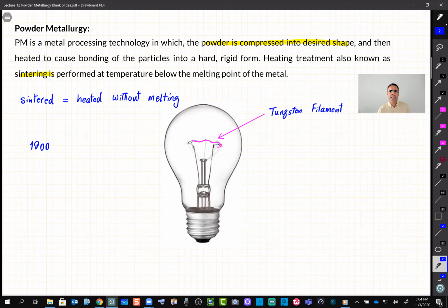Another thing that you may think of is a pen, maybe I have one here with me, a regular pen, which has one of those ball points. That tiny ball point, think of any other approach to make those tiny balls. For example, casting maybe is not a good way to make those, right? And machining, of course not, to make such a small sphere. So powder metallurgy is a common way to make those balls for the ballpoint pen.